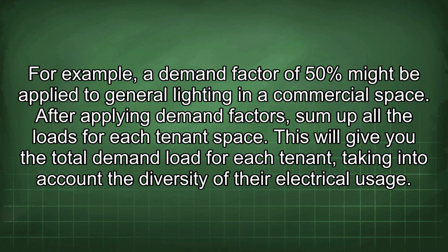After applying demand factors, sum up all the loads for each tenant space. This will give you the total demand load for each tenant, taking into account the diversity of their electrical usage.